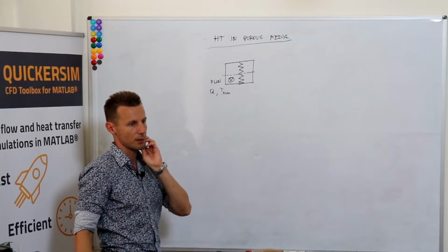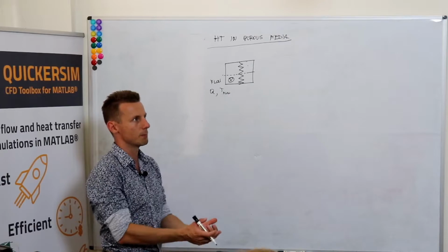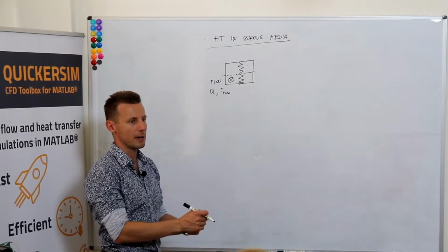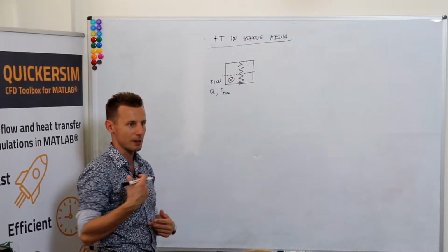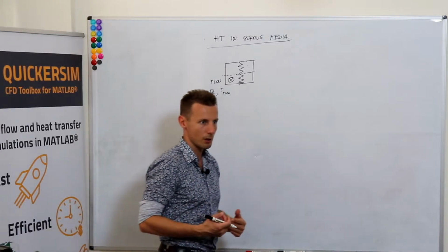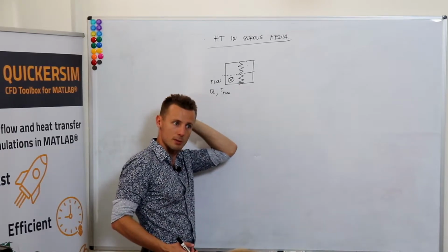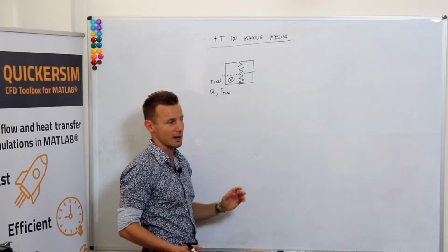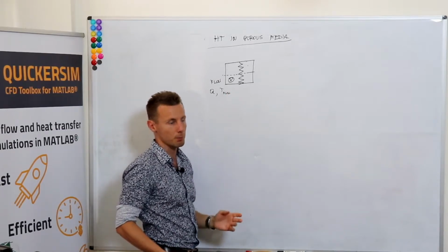In the Stirling engine you want to retain some thermal energy of the gas when it flows from one cylinder to the other, but then you want to take it out again when it goes back. So can you represent it by the porous medium? Yes, you can.